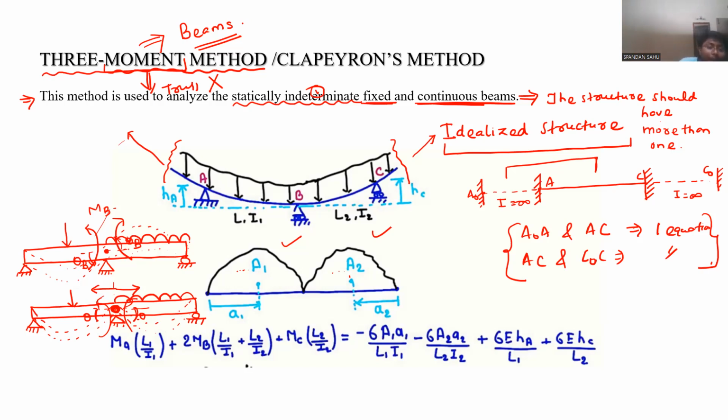But now you check. We have given a bending release, but in the real structure, do we have any bending release? No. Now from this, what compatibility is coming? Moment compatibility. Theta from this side should be equal to theta from this side.